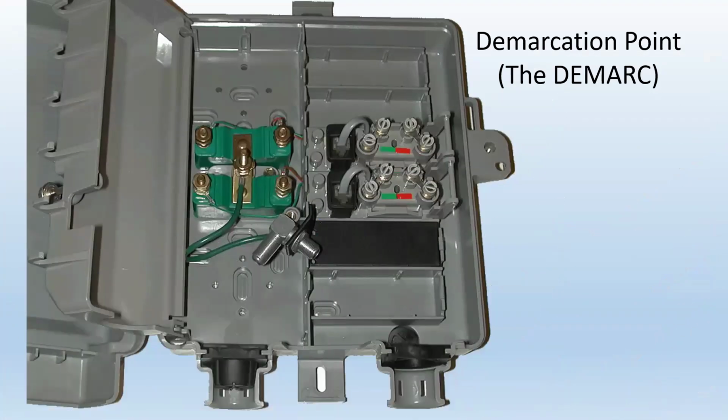Now, here's the demarcation point, point of entry. A box sometimes could be mounted on the outside of the house or inside of the house. Here's a tip and ring. Here's a tip and ring. This one is capable of two lines the way it's configured right now. This is a lightning protection. This looks like it's a plastic PVC, but it's a specifically formulated composition of material that when the lightning hits, is going to conduct current and it's going to take it right to the ground. So this part here is lightning protection.